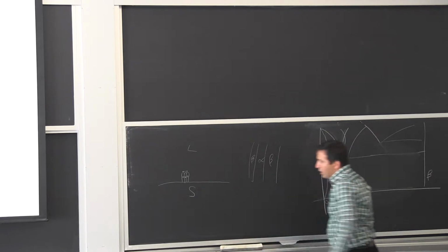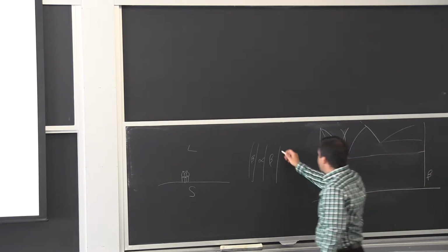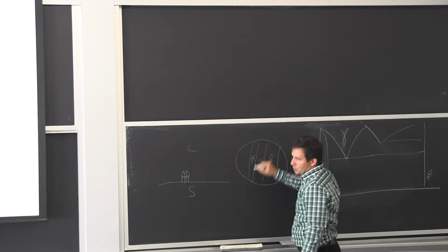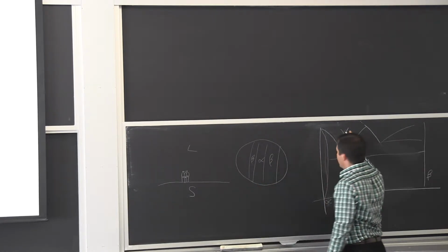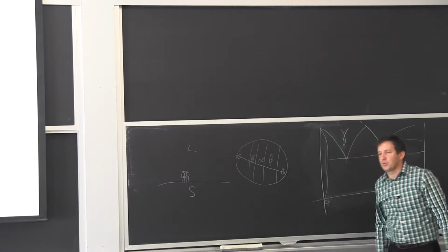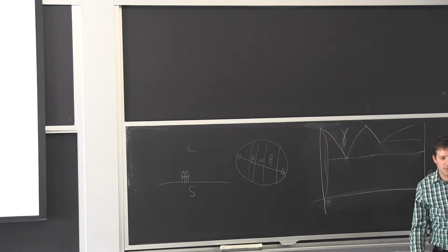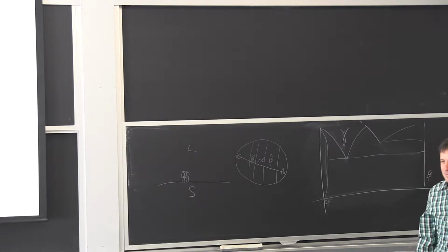So when we talk about hot working for steel, we only have one phase. And that's why we talk in the product about the grain size. We tend to think of it as the size of the austenite grain for controlling the structure. So what used to be one phase has a certain size, and that's what we think about in terms of grain size, even though it's multiple crystals. Well, I'll show some images. They're better than my drawings. All right.